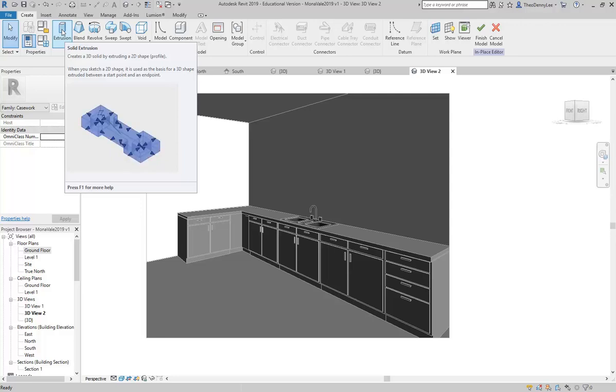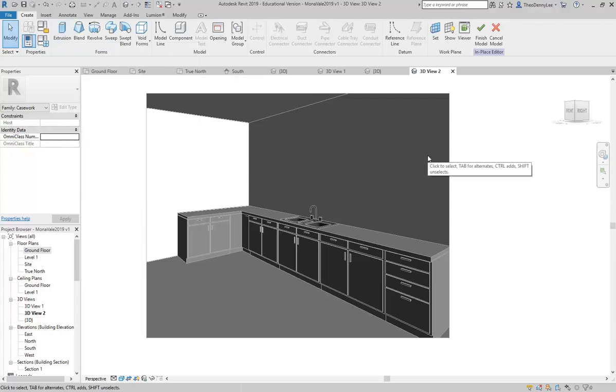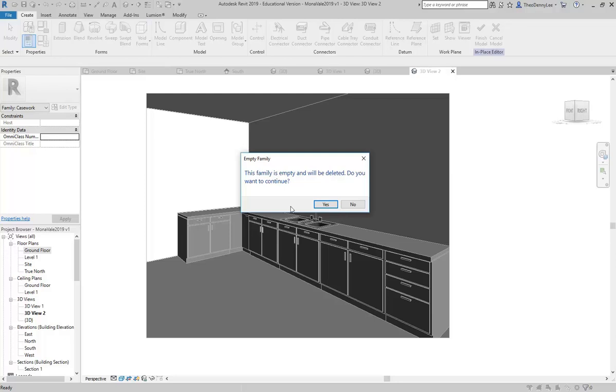They're just not always from the ground plane. They might be extruded from a vertical plane or something like that. And we'll get into that too, working in different planes. But yeah, lots of things you can do with extrusions. And sometimes you can just do a simplified version, just do a block form with the overall size of your object, and then later you can come back and add more detail. So extrusions are great, and pretty much most things are just extrusions to start, and you can do a lot with that.